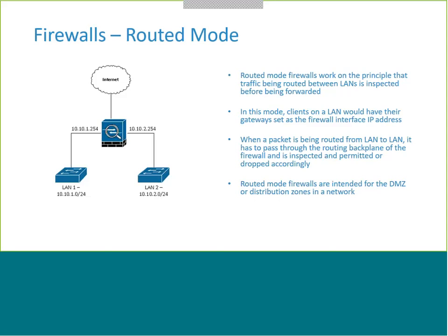And if there is no default gateway, then you add in an extra device, and then you could be faced with reconfiguring. Yes, exactly, which can be a real nightmare when you've got PLCs, workstations, HMIs, things like that. And there's been a lot of times where you have to reconfigure legacy kit and there's no one around who can do it, or no one's got a clue how this kit's even configured. I've seen that a lot as well. So it can be a bit of an arduous task doing that.